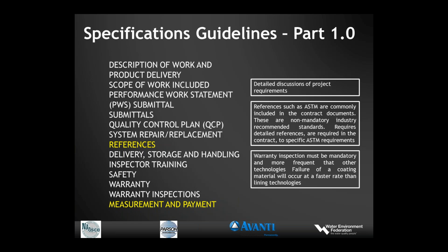As Lynn mentioned, there are two ways to do that. You either reference the chapter or the section of the specifications that is included in the contract, or recopy that section right into the contract documents. You can reference the ASTM, but define it right in the contract documents that these are the requirements of the contract. Because unless that is specifically cross-referenced, a lot of times contractors will not even pay attention to the reference specifications. So that's an important part to cross-reference in the actual documents.